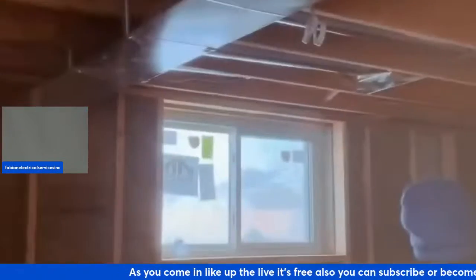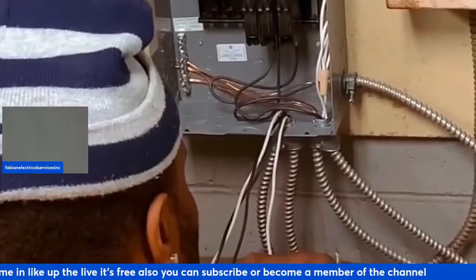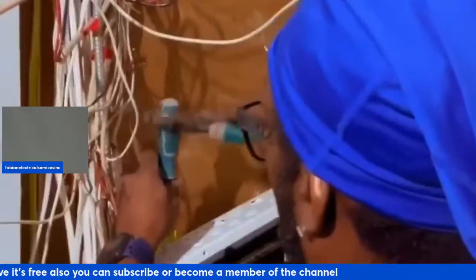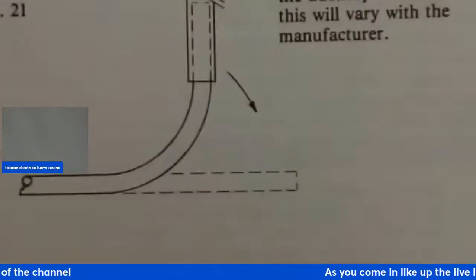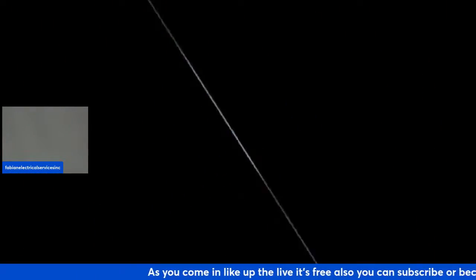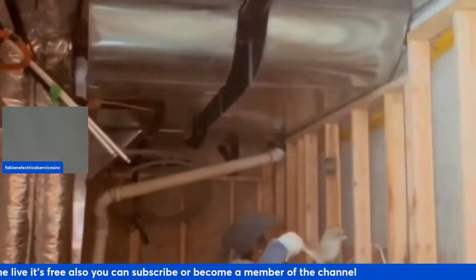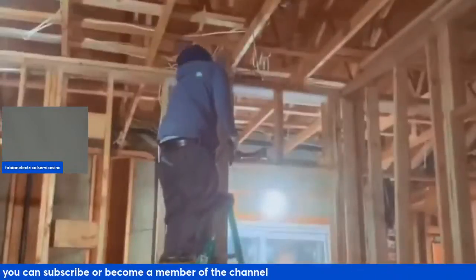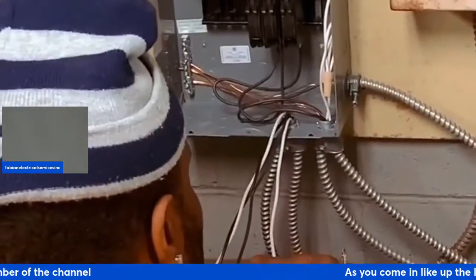And the safety measures. Dangerous arcs can occur due to broken wires, pinched cords, or loose connections, and can produce enough heat to ignite surrounding materials. It will then trip the circuit. When an unsafe arc is identified, the AFCI opens its internal contacts to quickly shut off the flow of electricity to that circuit, stopping the risk of a fire.